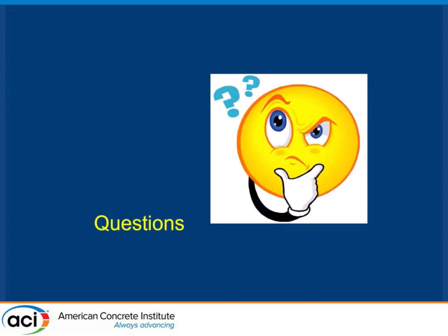Any questions at this point? Yes, sir. Just wondering about the pryout. You just mentioned the embedment. Is that not addressed in 318? I know it's a nice little piece of information, isn't it? But it's addressed on how far down. I mean, you can calculate the capacity for pryout, or what you get to.